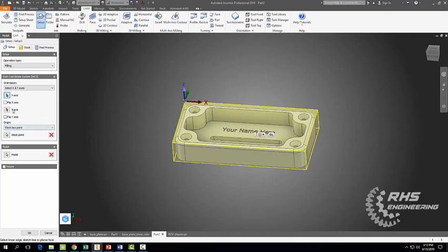And if they're still not orientated correctly, then you can flip X and flip Y to make sure they're right. Once again, you can do the same with Z here. You can select your Z plane too. You just hit this and you click right there because this is our Z, this white line.